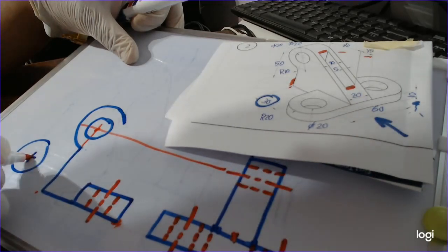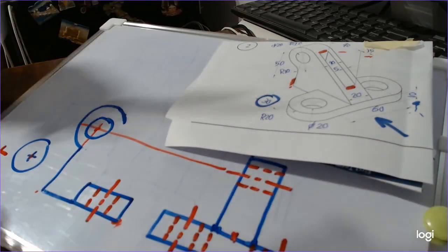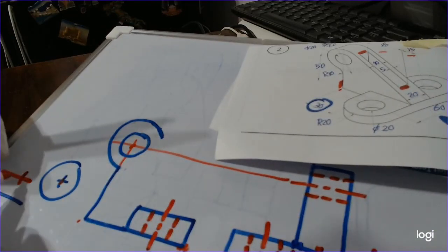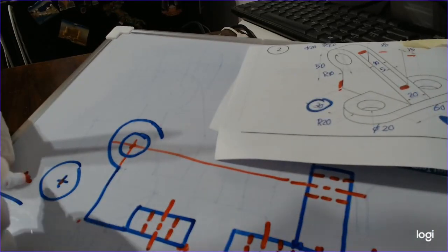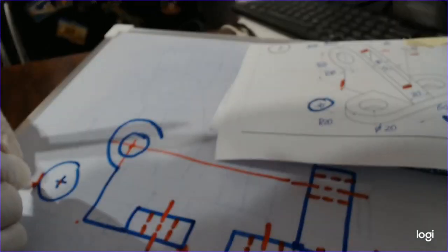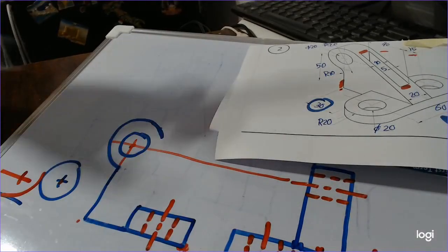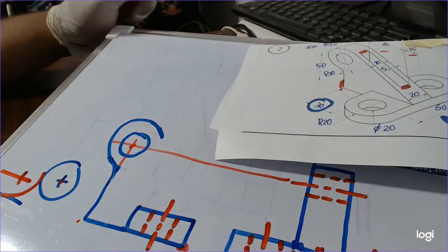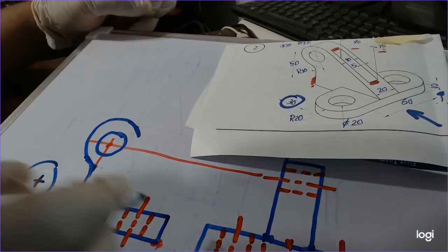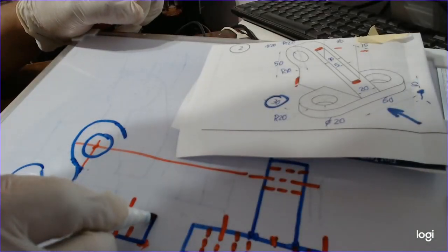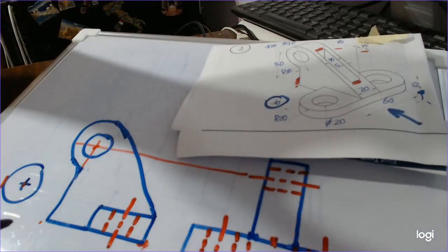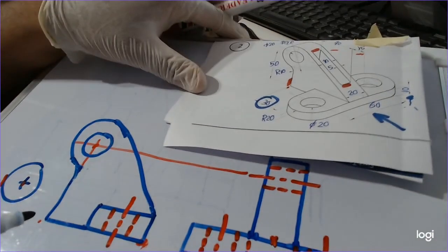So we'll put the tip of the compass here, and we'll open 30 millimeters, and we'll make a notch here, and then put the tip of the compass here and open 10 millimeters, and then we'll make something like that. So this one will be simple. Okay? Then we can draw a tangent point from this line to that circle. We said the steps before. And now we are missing the pocket, okay?